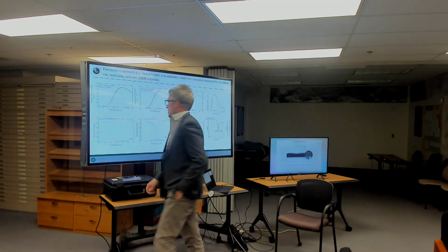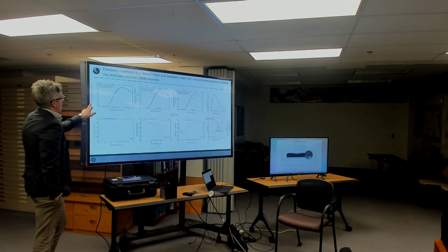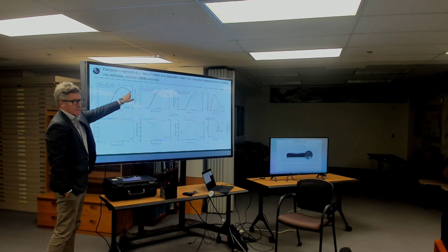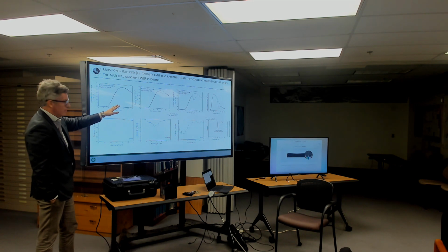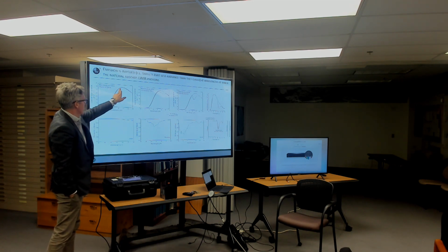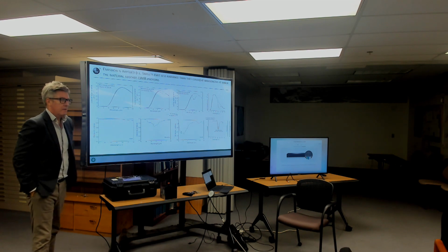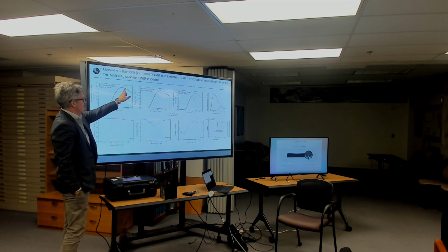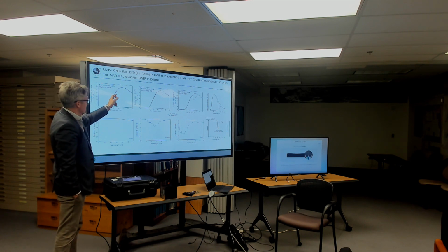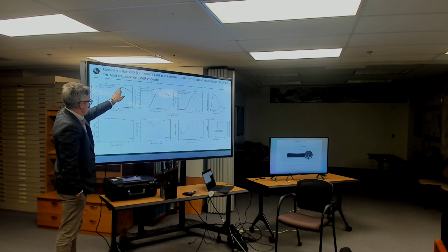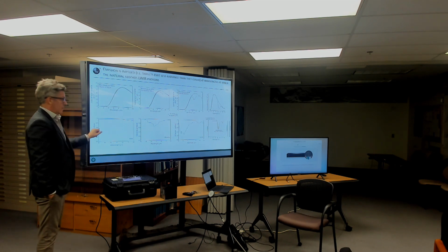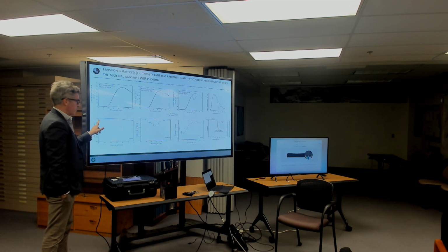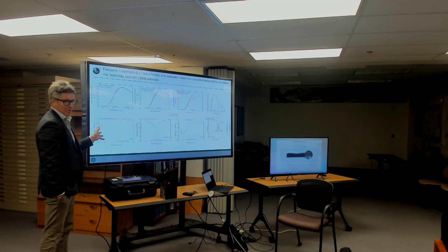So just some examples of what it's looked like. So again, spectral radiant excitance for a black body at 300 Kelvin is the black curve, which I just compute from Planck's law. And then the red is water at 300 Kelvin, which is a measurement. So water actually behaves very close to black body behavior. You see, the red curve is really similar to the black curve. It's just a little bit below here. And if we divide red by black, we get the emissivity of water. And we have this curve, which isn't that different from a black body curve. So we would call water a grey body, which has nearly black body performance.